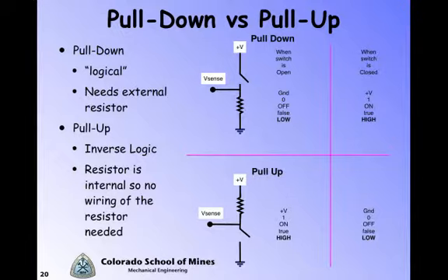That is, when you read high, you think open or off, and then when you read low, you think contact switch closed, on, and in the case of lab 3, the bumpers are actually in contact.